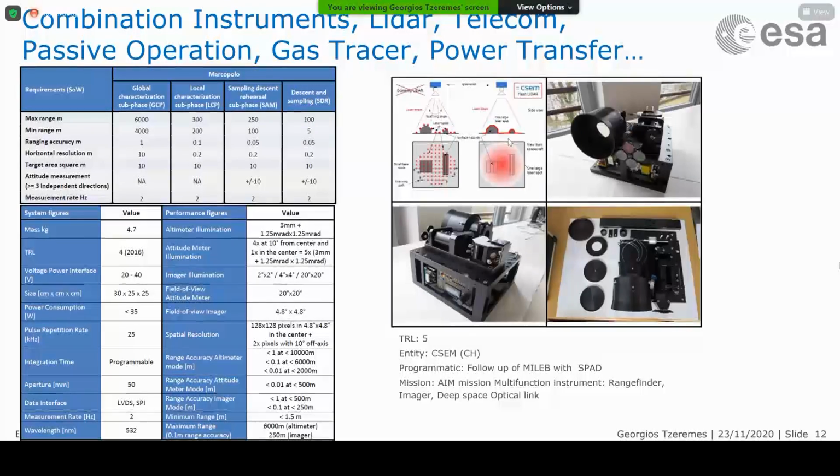The benefit is that it's much faster, and it covers much better the whole region of interest. The biggest drawback of this system is that it's not easy to regulate the field of view, which you can easily do with a scanning system. There are solutions to this. For example, as you can see on the right image, we have different beam expanders. We can mount different beam expanders for the laser, and then you can have more options for the field of view in the system.